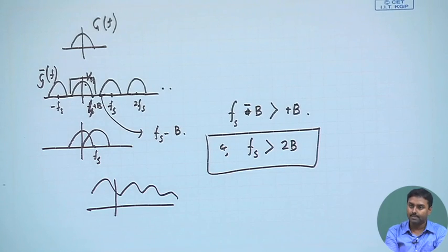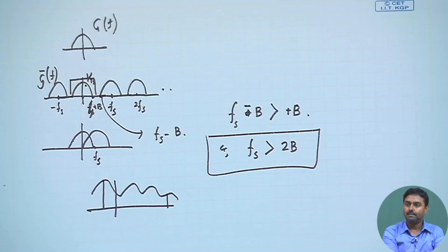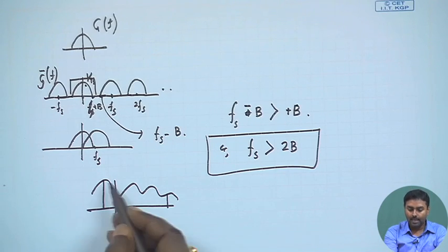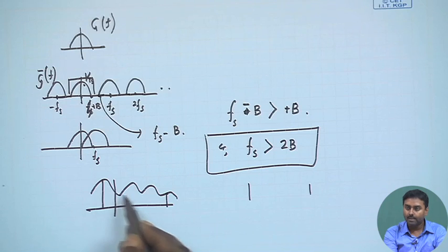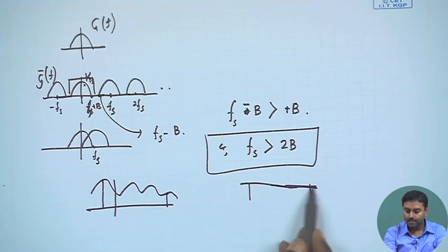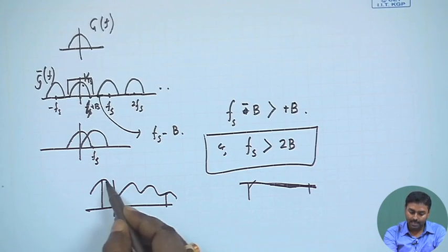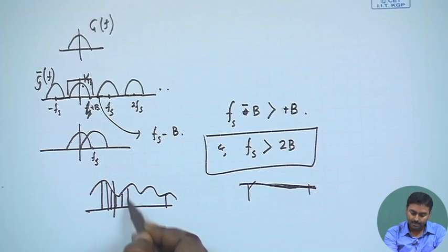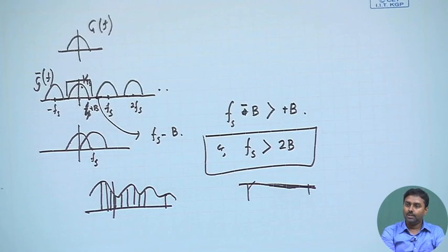This is quite obvious. Suppose I have a signal something like this, and then I just take the samples like this. What will happen if I try to reconstruct without knowing what has happened inside? I will just reconstruct it this way, so it will take out all the variation, whereas if I start getting samples like this, it will capture the entire variation.